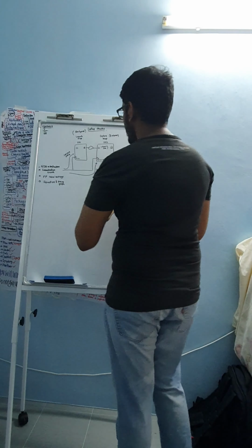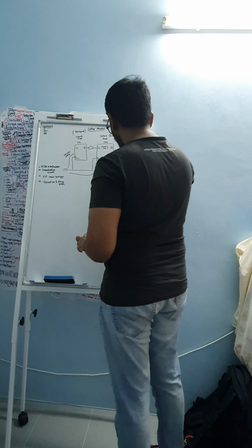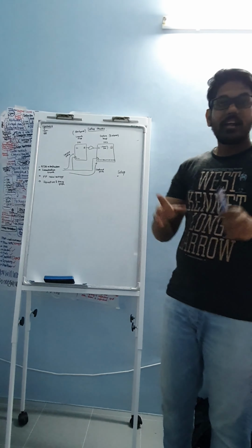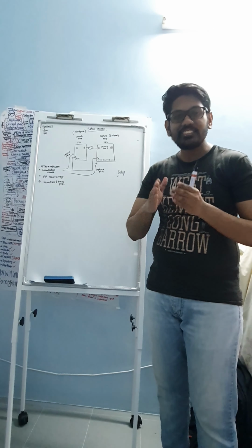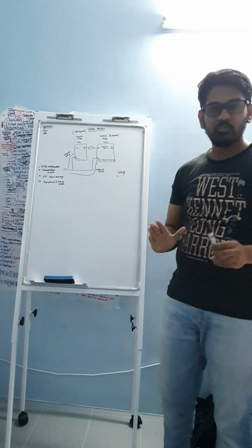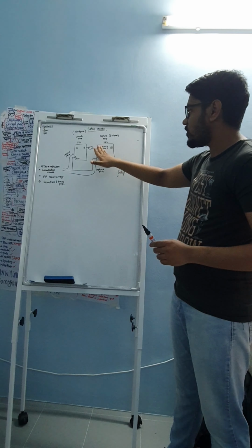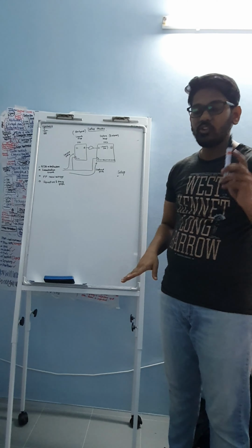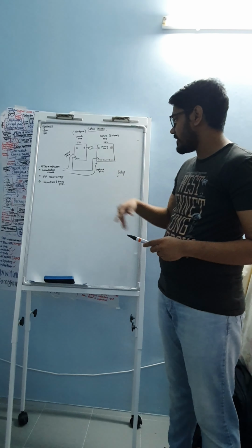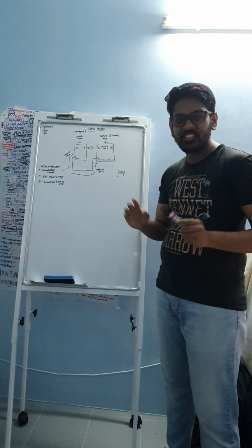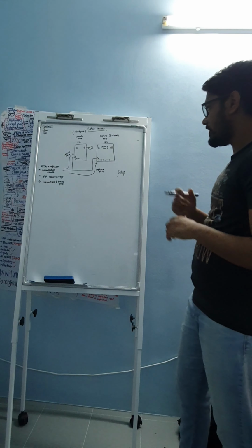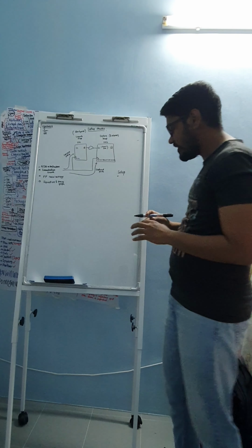Over here you need to understand the definition of setup checks. You have to know that the data has to be stable before the next clock is triggered. You really have to make sure your data is not too slow. If your data is slower than your clock on the next clock edge, then you are going to have a setup violation. So it is important for you to know this.